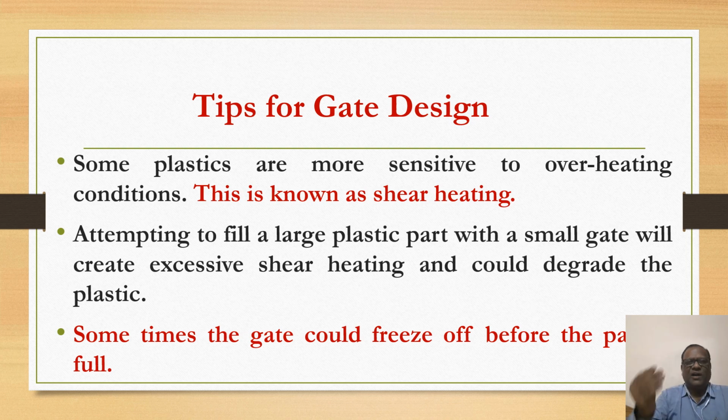Actually, it is required to freeze the gate, but only once the cavity is filled completely, so that the flow from the nozzle side will be stopped.